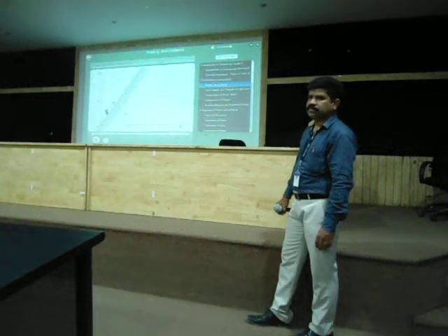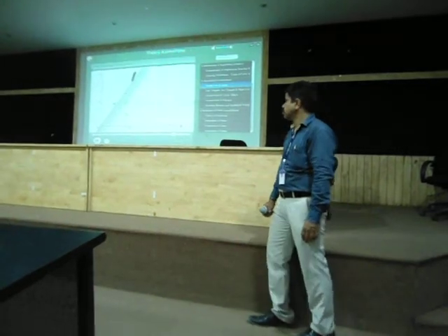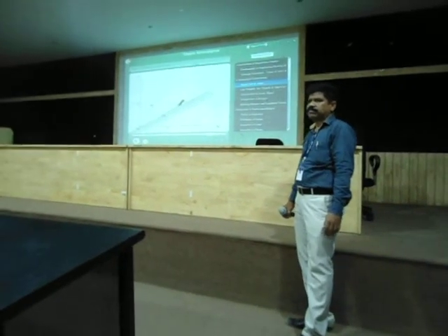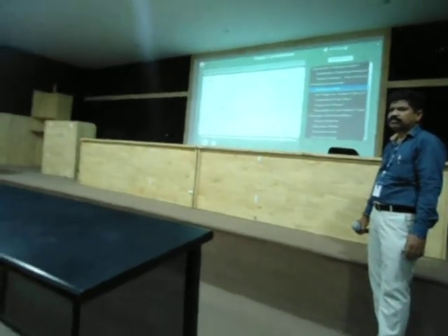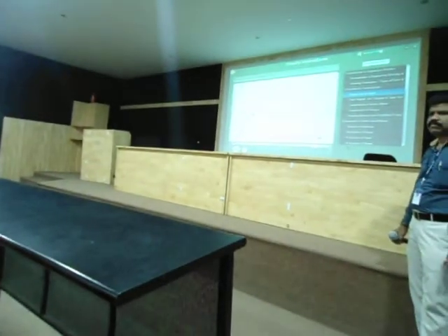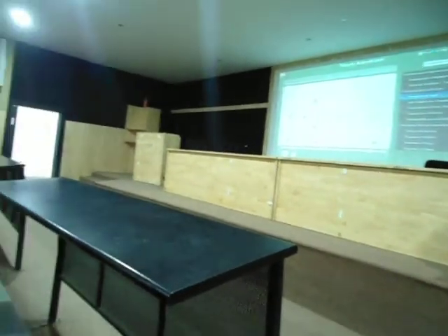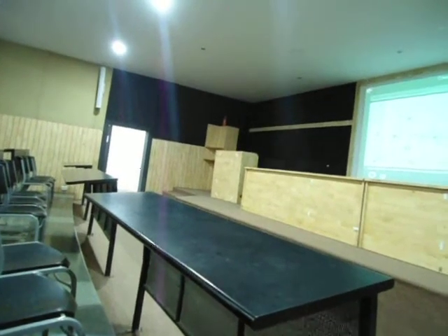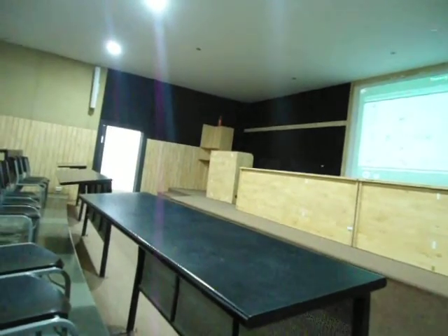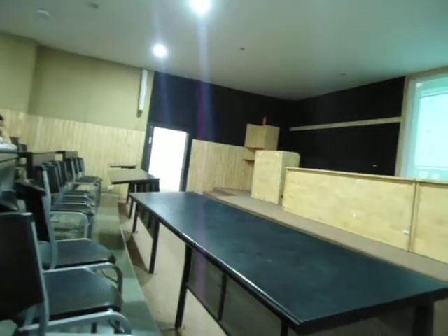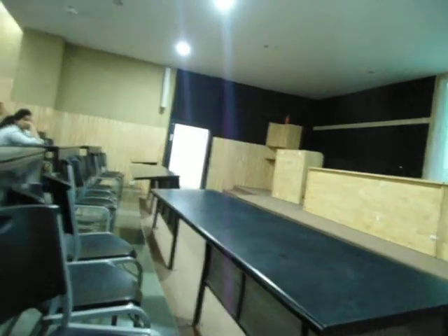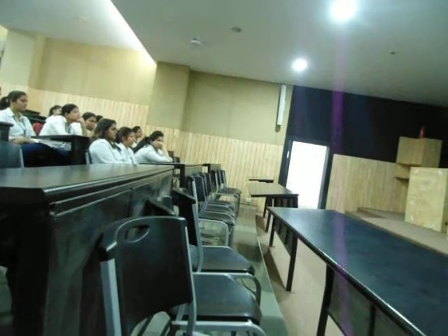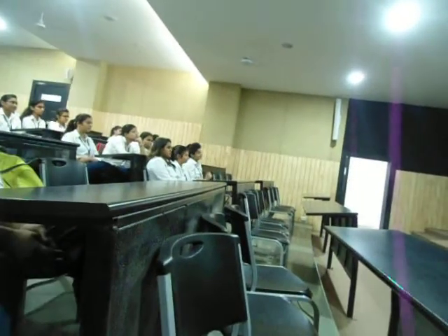Now join AM and extend it till it is long enough. Similarly, join line AN and extend it long enough. Their intersection points with the outer arcs are M dash and N dash. So this is how we have created lines AM dash and AN dash that divide the angle CAB into 3 equal parts. If you measure them, they will be 30 degrees each.